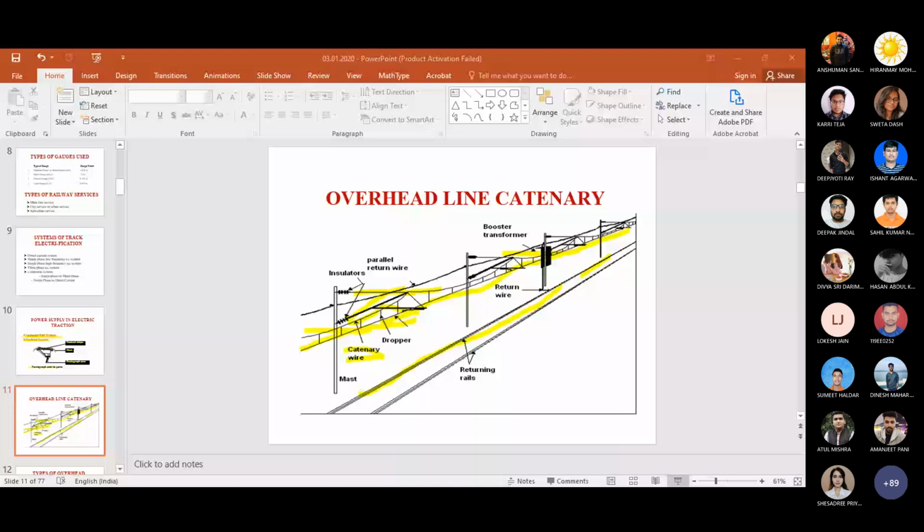Basically, there is a rate of change of cutting flux, and the direction of that induced EMF opposes the current. The current is the cause, and the induced EMF is the effect. Current flows through the armature winding in the motor, so an armature magnetic field is developed.